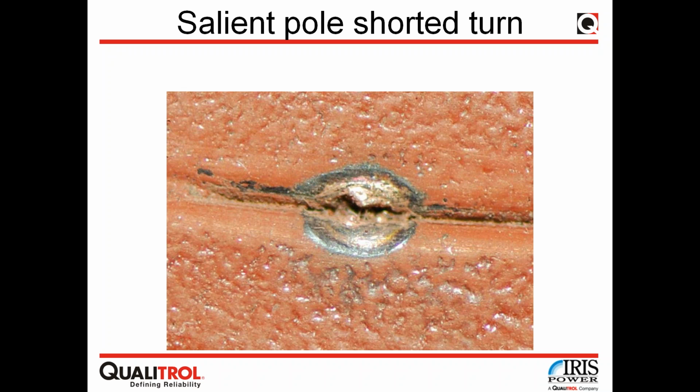So the approach for installing flux monitoring on an explosion rated motor is to put the probe inside and bring the box to a place where there is no rating anymore. So the answer is yes, that way. On a PD, the approach is similar: the installation of the sensor needs to be done in a manufacturing process, so as not to affect the rating of the motor. So in that case, it is possible to use the same approach to monitor explosion-proof rated motors for PD and for flux.